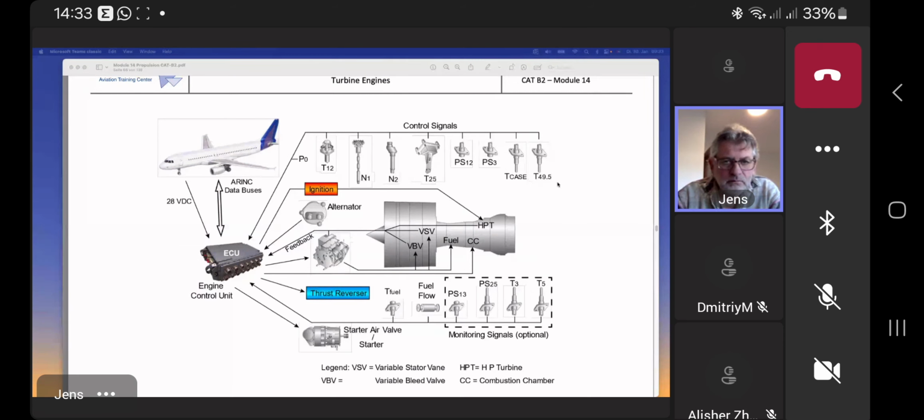As soon as the engine gets older, the clearances also get bigger and bigger. So the compressors lose a little performance, and the turbines lose a little performance. And the only way the engine can react in order to gain the requested thrust is to enhance the fuel flow.